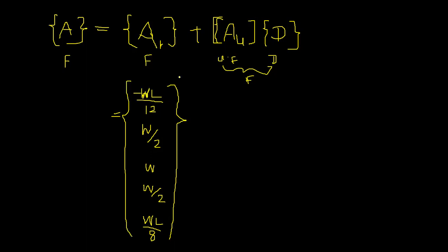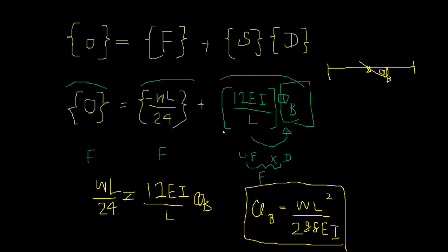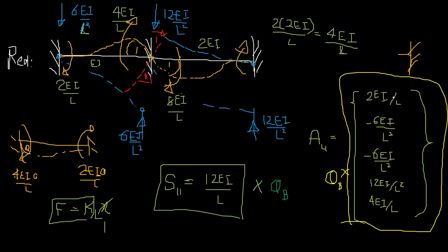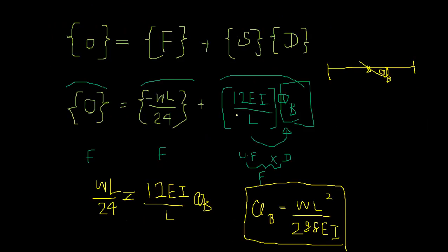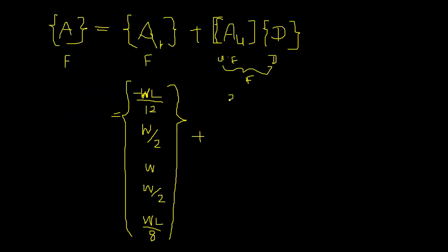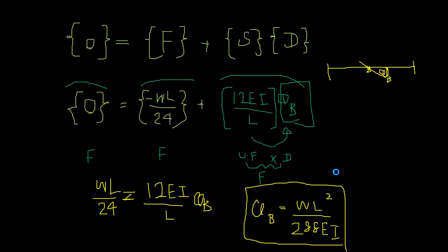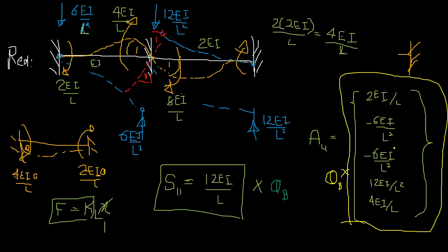We substitute QL as W, right? That's why it is easy to simplify. Else it's a bit difficult, right? Q and W terms, right? So this is going to be 2EI over L. 6EI over L squared, 6EI over L squared, right?